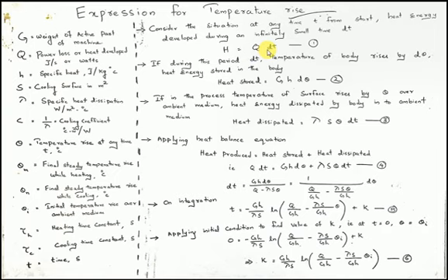During this short period dt, the temperature of the body rises by d theta. So definitely some amount of heat energy will be stored in the body of the machine. So let's obtain the expression for heat energy stored in the body of the machine. You have already studied this relation in your school classes. The heat energy stored by a body is given by m c delta theta. You are very familiar with that relation where m represents the mass, c represents specific heat, etc. The same relation we are showing here also.